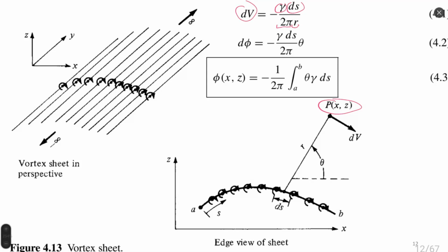So we obtain equation 1, which is the change of velocity in any arbitrary point, proportional to the strength of the vortex at each specific point, the distance where this vortex is working, and inversely proportional to the 2 pi coefficient and r, the distance from this specific point to the point where we are looking at velocity change.